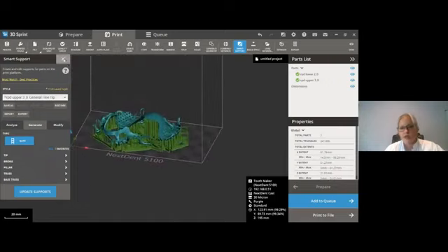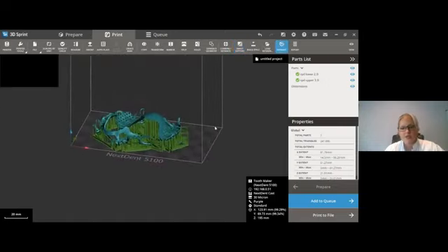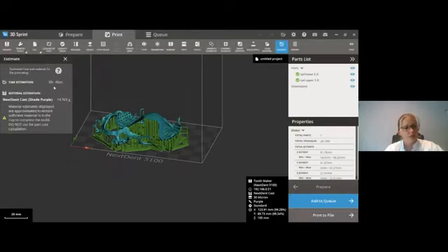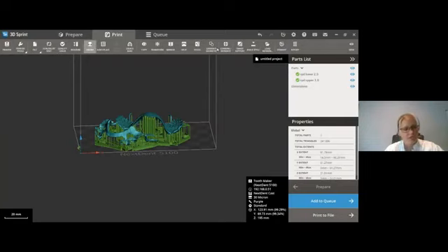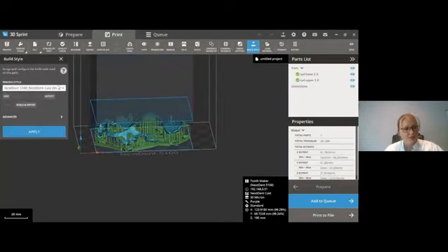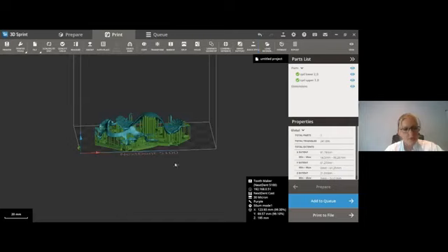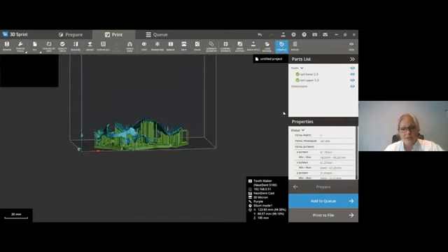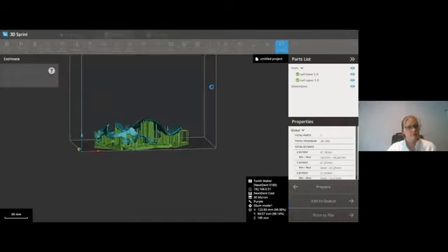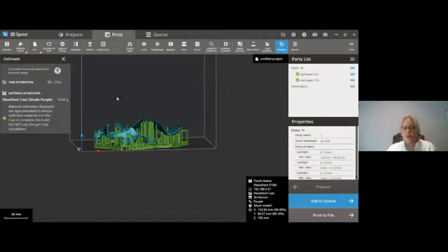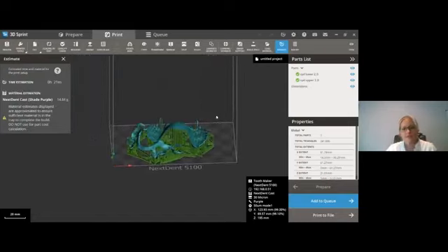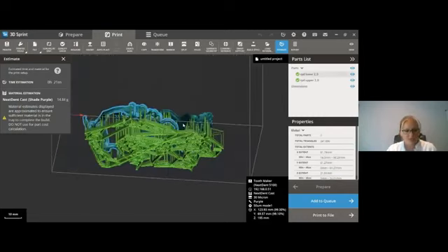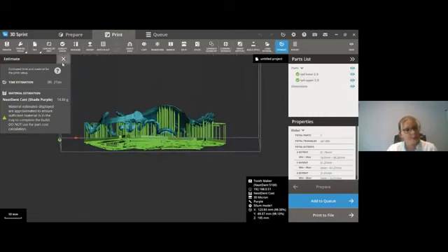Okay, so let's take a look here at the estimate. And this is what you guys are all used to utilizing. Okay, so we have a 46-minute build here. Now, if I change my build style, which we would change over to 50, and I'm just going to do it right from here, and now I re-estimate, it goes to 21. That's over 50% faster. So you're going to be amazed, and it does not actually decrease the quality whatsoever.